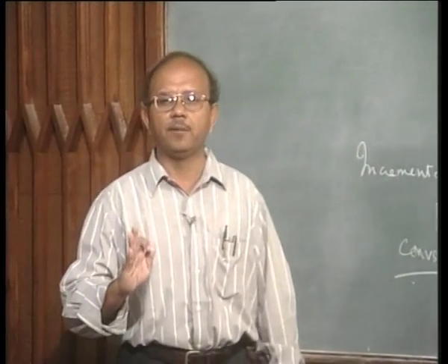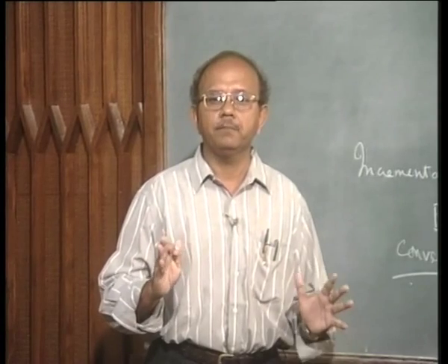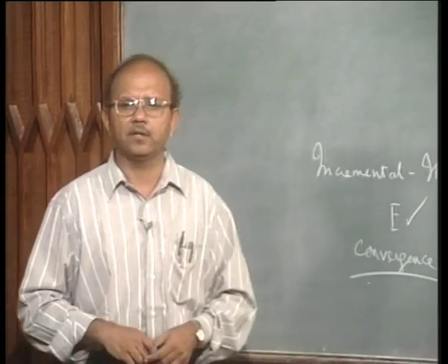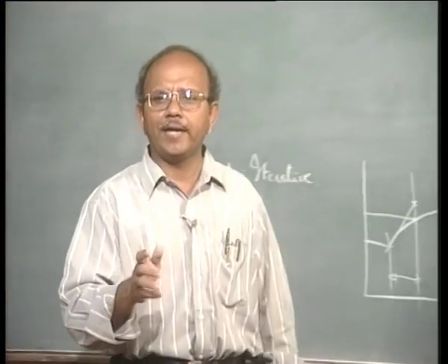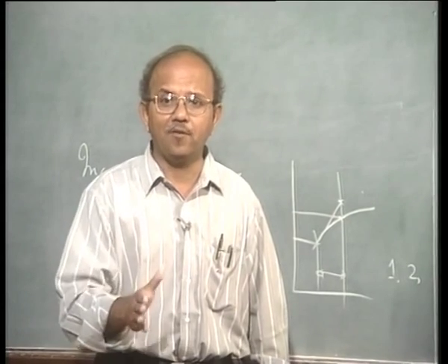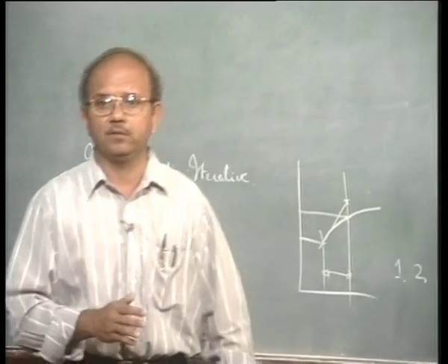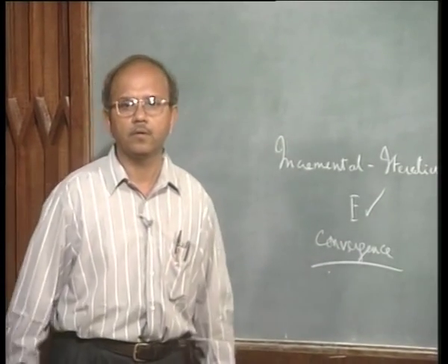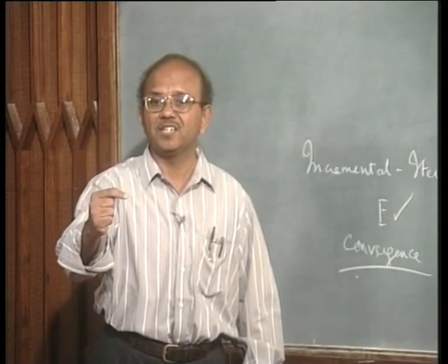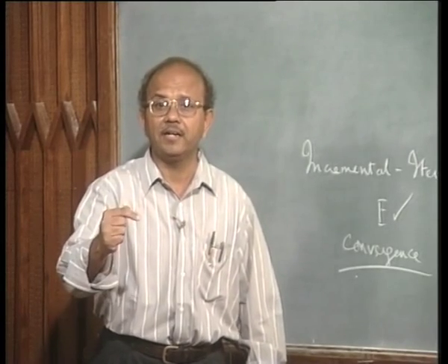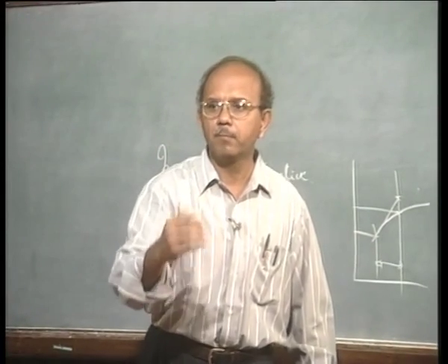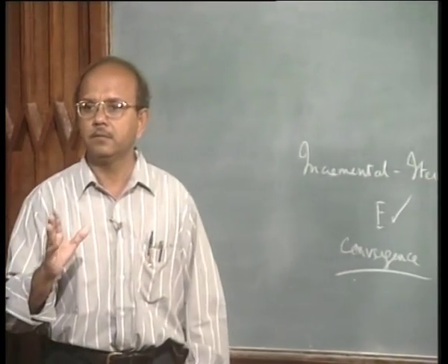See, let me say for example that I am applying a load of 1000 in 10 equal increments for the time being. So if I is equal to 5, I am in the 5th increment. That means that I have completed 5 increments. Then I have already applied 500 Newton. Now from 5 I am going to the 6th increment. That means that from 500 I am going to apply another 100 to go to 600. Is that clear?